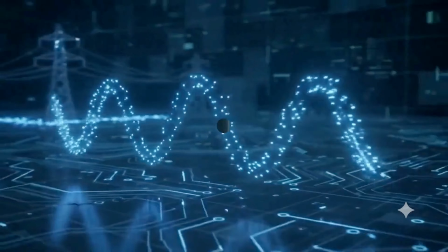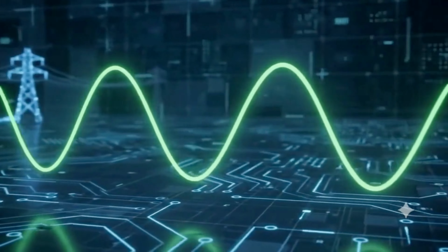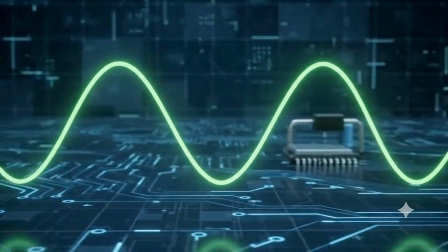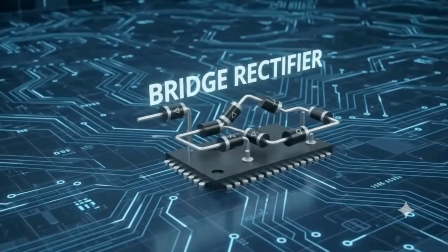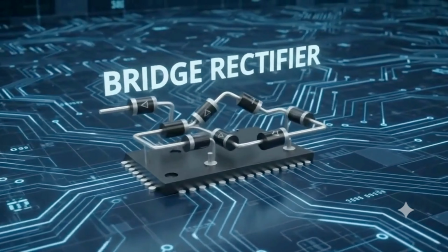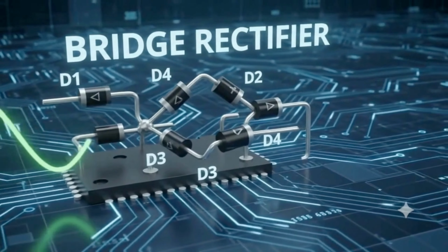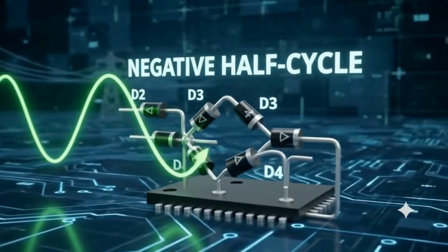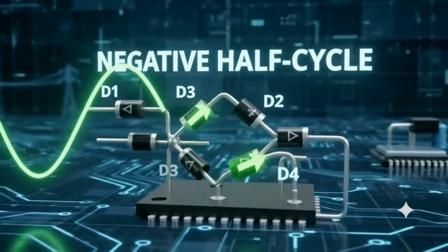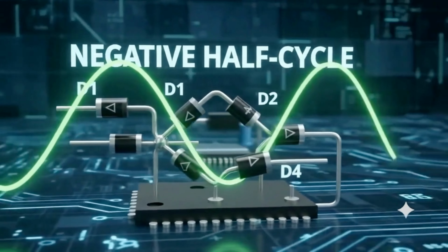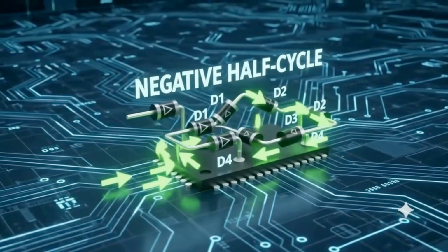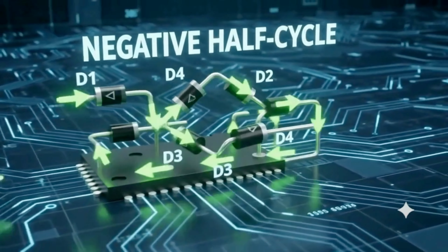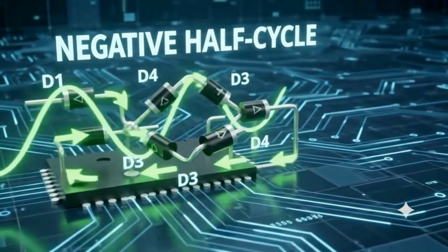Electricity from the grid travels as an AC sine wave. A bridge rectifier converts this into DC. It uses 4 diodes labeled D1, D2, D3, and D4. During the negative half cycle, the opposite diodes D3 and D4 conduct. Notice that the current is redirected in the same output direction. This process creates continuous DC power.